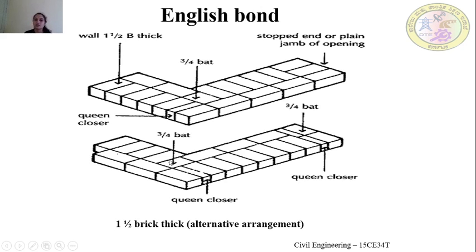And in the back we can observe, imagine this is the AB line, and on this AB line we have the facing finished. We have done with the facing, and when it comes to the backing, since this is 1.5 brick thick and this is only 1 brick thick, we have placed one more brick stretcher-wise so that it becomes 1.5 brick thick.